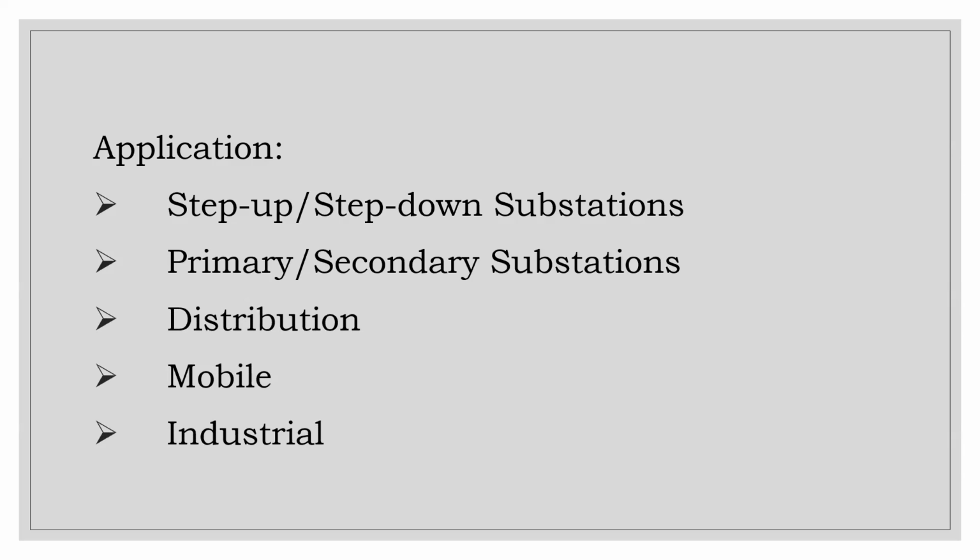All right? So you have step-up substation, step down. The only purpose of these substations is to move the voltage from one level to another, and vice versa. So we bring it from one level up to another, or from one down to another. All right, so we are either bringing it higher or lower. Okay, and the voltage at which you'll be supplying your energy will have certain requirements. In terms of the space in which you're operating, you may not be able to have a 138 kV line, for example. I'm just throwing that out there. So you may not be able to have a 138, but you can have a 69. So to go in a particular direction, you have the 138 coming into the substation, you bring it down to the 69 and move it on.